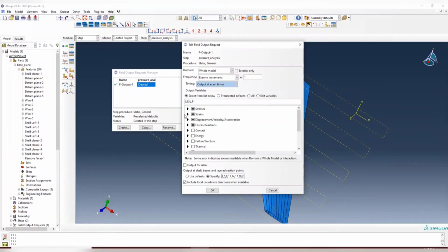So you can consider your ply as 3 points interpolating each ply. So in total, we have 10 plies for the composites. And we only output the results from the middle of the plies, which is integration point 2, 5, 8, and so on. And we should have 10 of that. 1, 2, 3, 4, 5, 6, 7, 8, 9, and then we need one more, 10.